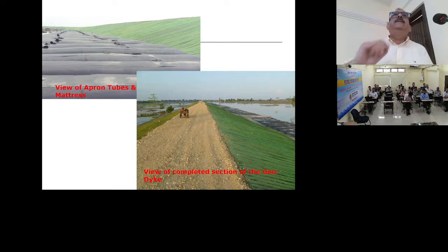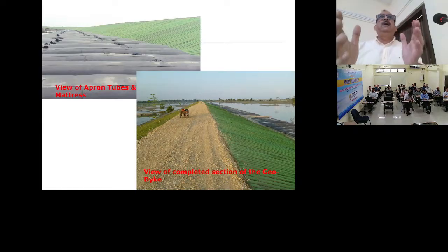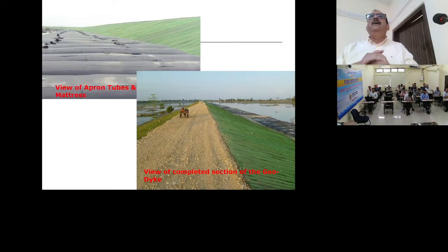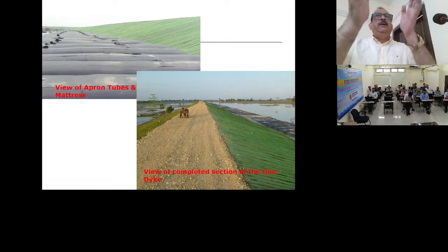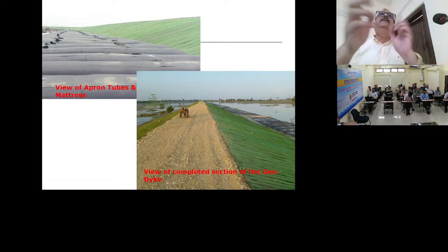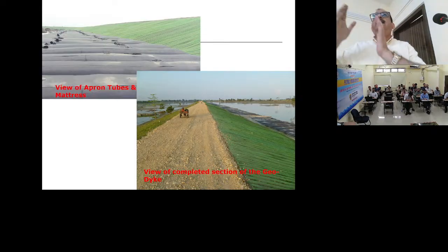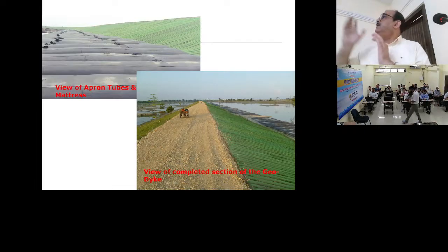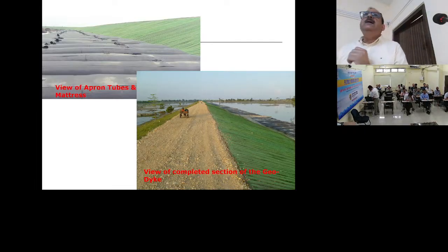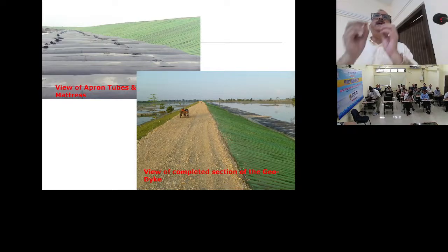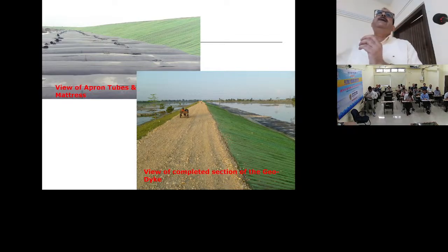There are two bridges. And then during flood time, actually, we were invited to go there. What to do? Huge amount of water is coming at that time. These measures will not work. Then we placed one geotube during flood time, and then filled it up with sand, and the whole area was protected. Water was entering the villages, so that was stopped. So very effective, because with very less time you can implement these things.